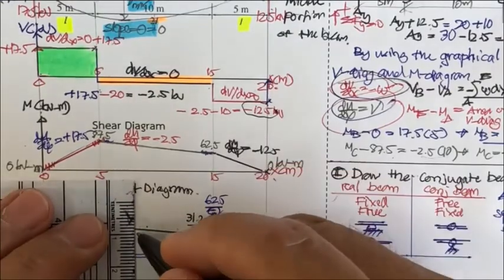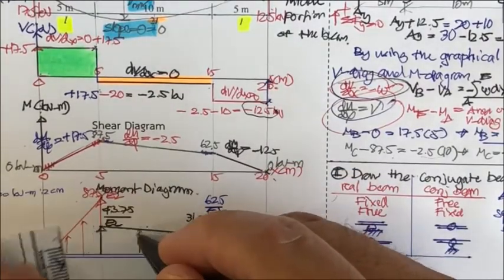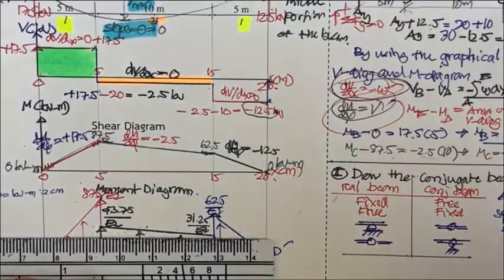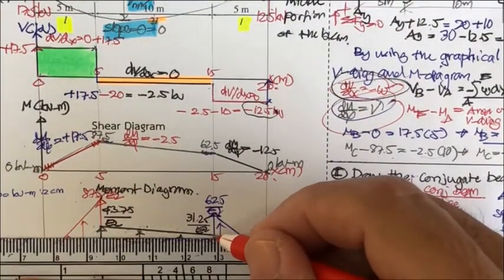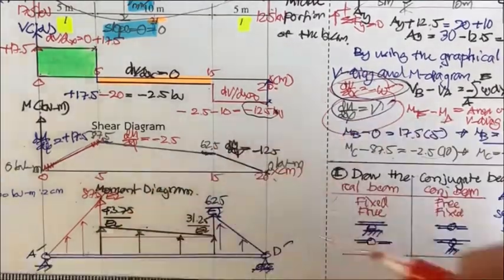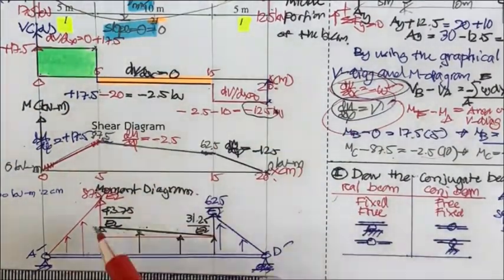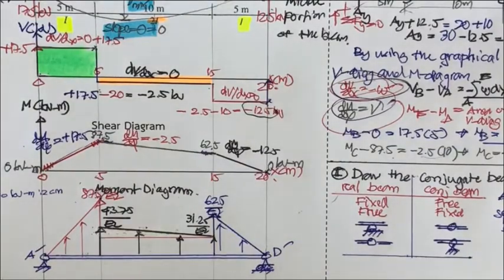Now we have what is called the conjugate beam, and we have 3 portions of elastic weight. One is the red one, another is the black one, and the other is the blue one. However, at the middle part, we should separate them into 2 parts. One is going to be this one, and another is that one. Let me pen this one a little bit.